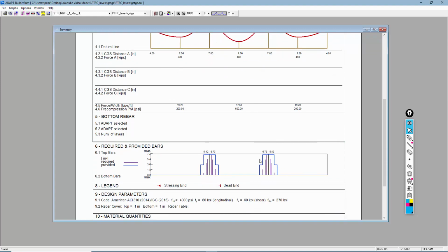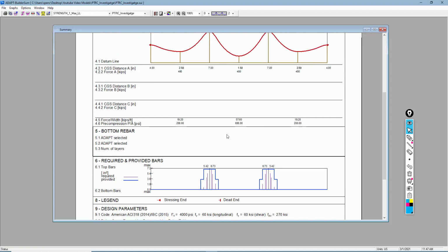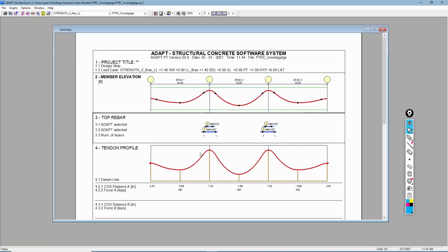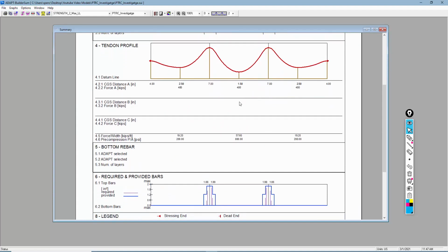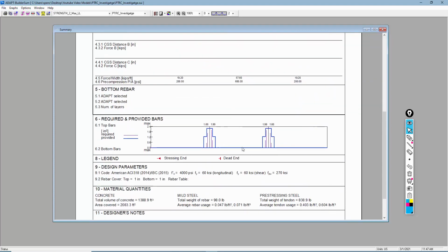This is what would be required in area of steel, in more decimal, numeric format. These are the areas required to meet the demand. This is in addition, again, to the user-defined rebar and the post-tensioning. So that's only for strength 1. If you look at strength 2, then this is a separate result. So here we need 7s. This is 1.4 times dead load. The other is 1.2 dead plus 1.6 live, and this shows us similar results.